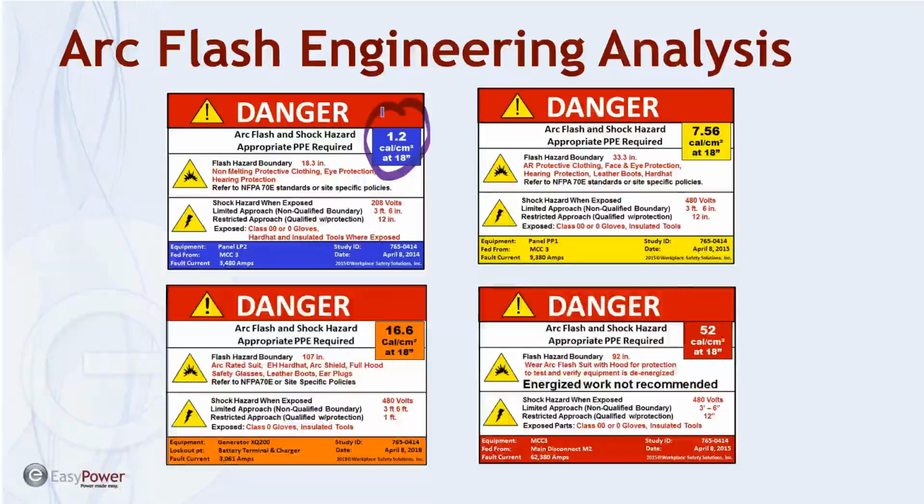It's got a 1.2 calorie. We'll still have danger. And I've been questioned by OSHA on this, and dropped it pretty quickly because I let them know that there's still a shock hazard. If the panel is open, there's still a shock hazard, and that's a dangerous condition. And they say they're okay, and they're fine with it. So we put danger on ours, and we put the ANSI symbols, and so we meet the ANSI Z535 standards.